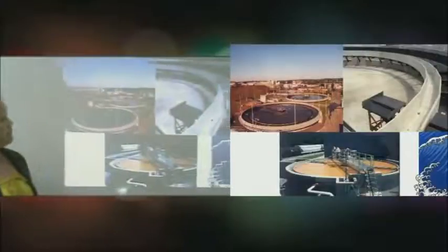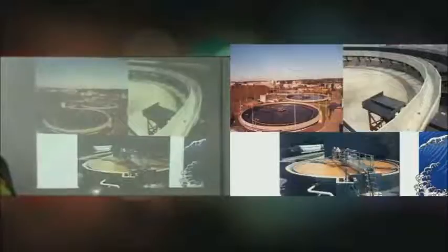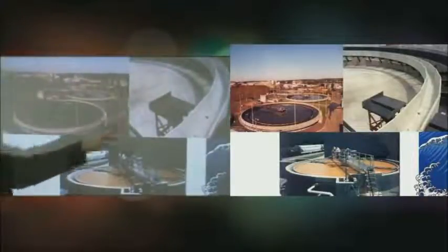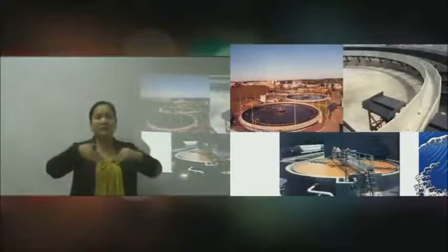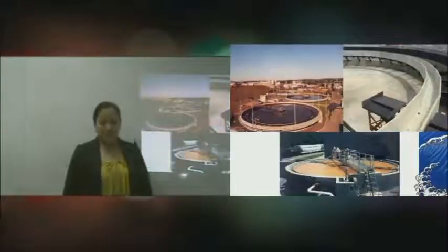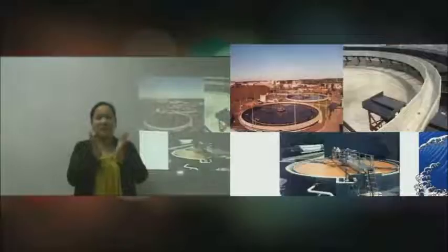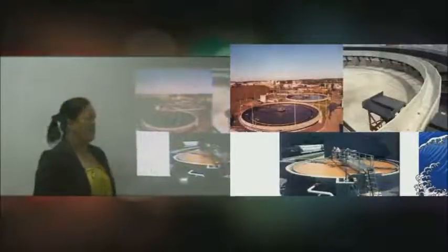This is an example of an STP, or sewerage treatment plant, clarifier. So you know in this class that the clarifier would be somewhat in a conical shape. Why? So as not to use any pump anymore. You remember the funnel? It is designed something like that so as to facilitate the separation of the floc from the effluent.